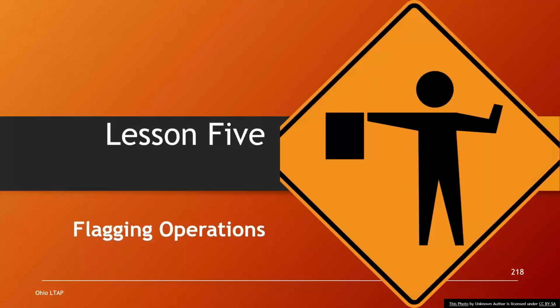If you have a 4-lane divided highway and you want to close a northbound right lane, and you're going to use typical application 33, how would you determine how long of a merging taper you would need? So the question is, how long is a merging taper for a 55-mile-per-hour design speed? Do you all remember how to figure that out?